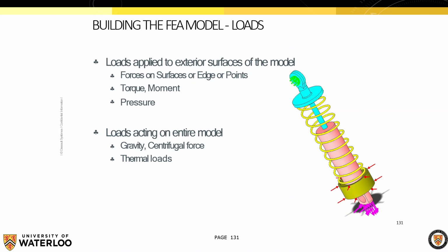Loads are something that I think everyone can appreciate is an important ingredient for the model, where you're applying forces on surfaces, on edges, on points. It could be a torque, it could be a moment, it could be a pressure. You could even have different types of loads like gravity, centrifugal forces, thermal loading, like your colleague here was probably going to need in their housing analysis for that thermal event.